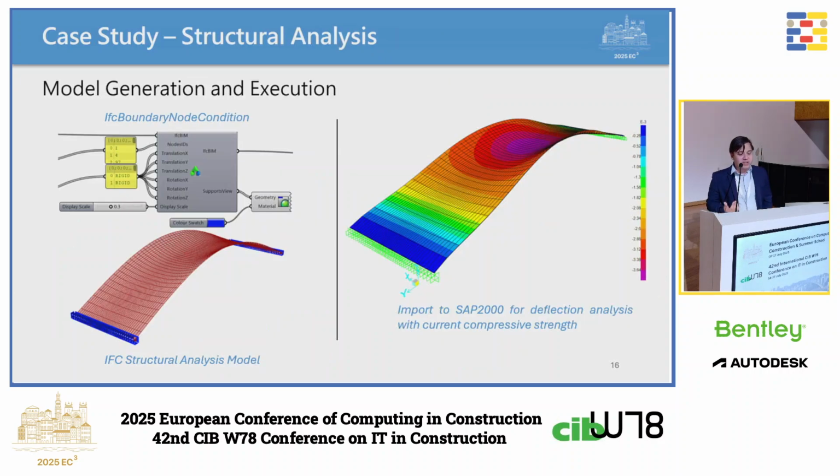And if we want to gain more insights, not only the updated mechanical properties of the concrete, we can generate a structural analysis model and import it into SAP 2000 to perform a deflection analysis with the current mechanical properties of the concrete.